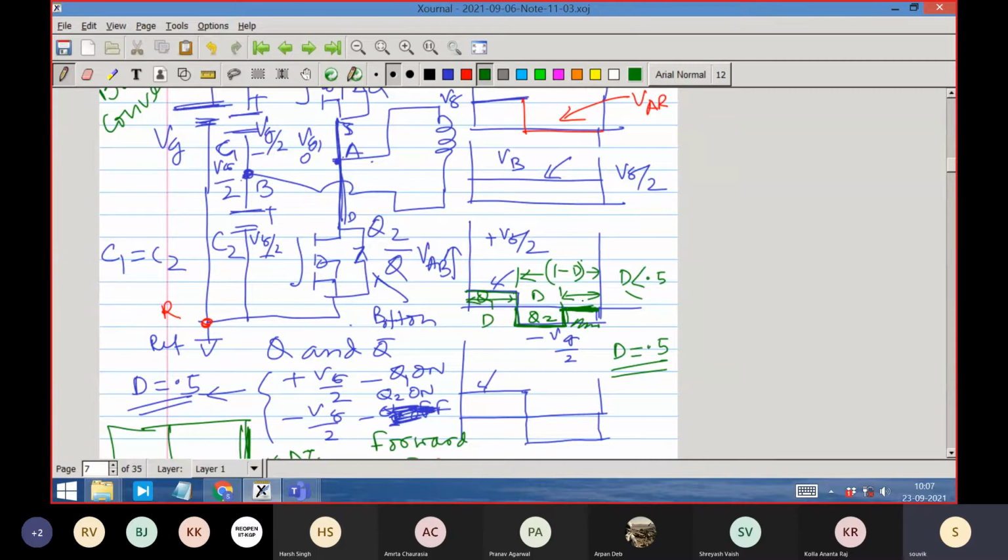And how do we again get the control of the output voltage? We again get back the control by adjustment of the duty ratio. That is what I said. Duty ratio is a control variable. So we must possess the flexibility to choose our duty ratio. It should not be frozen at certain fixed values, because it may work at a certain fixed value for a certain fixed input voltage. But in power converters, everywhere our objective is to ultimately regulate the output voltage irrespective of the input voltage. That is what our objective is.